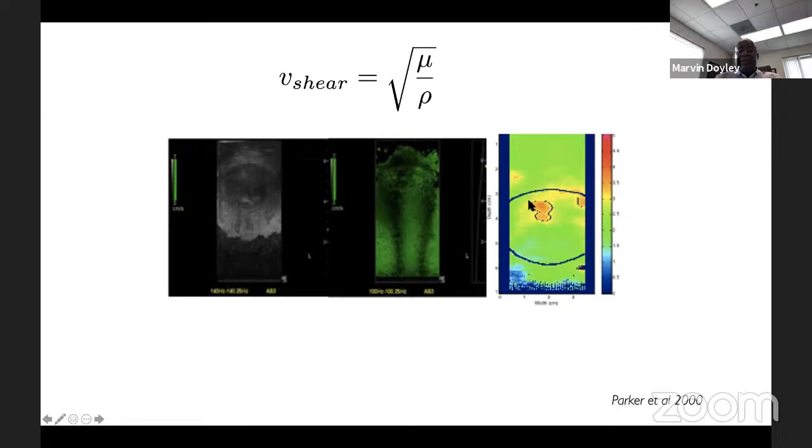And then once you know the shear wave propagation, you can work out the shear velocity, and there's a nice relationship between shear velocity, shear modulus and density. Based on that, you can calculate the shear modulus locally and create images like that. Now, the main drawback of this technique is that for it to work, you have to have a nice plane wave propagating. If you don't, this will break down. It's pretty hard to calculate the shear wave speed and in turn the shear velocity.